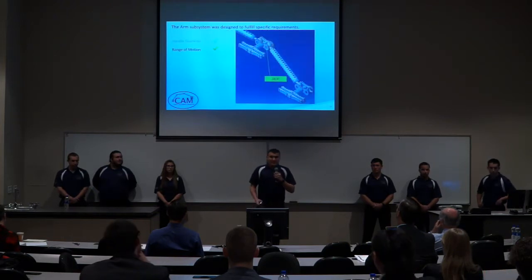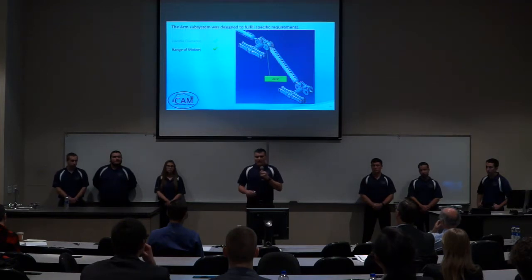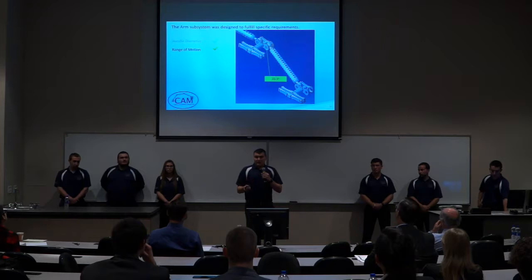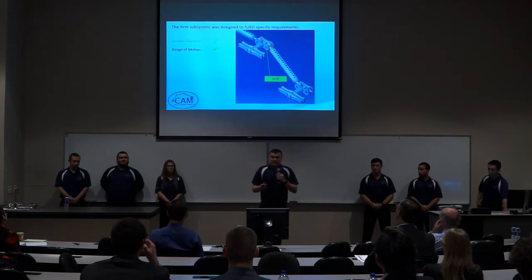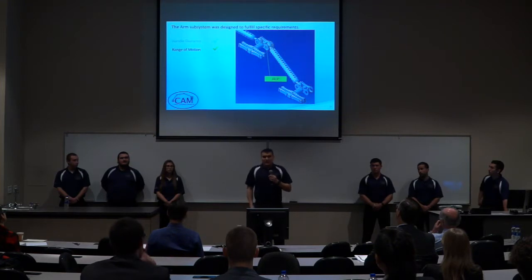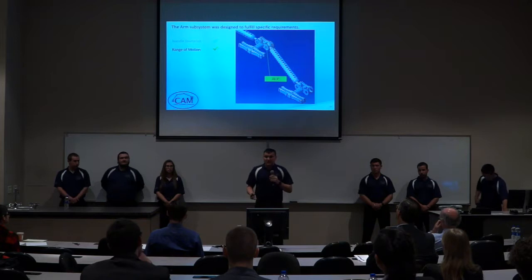The second design requirement that we fulfilled was the range of motion requirement. This ensures that the camera mount has at least 45 degrees of freedom of motion in all 3 dimensions. With this double ball joint design, you can see that in its most limited axis of direction, we achieve a range of motion of 22.5 degrees. When you take into account that this happens on both sides of the double ball joint, you get a maximum displacement of 45 degrees, thereby fulfilling this requirement.